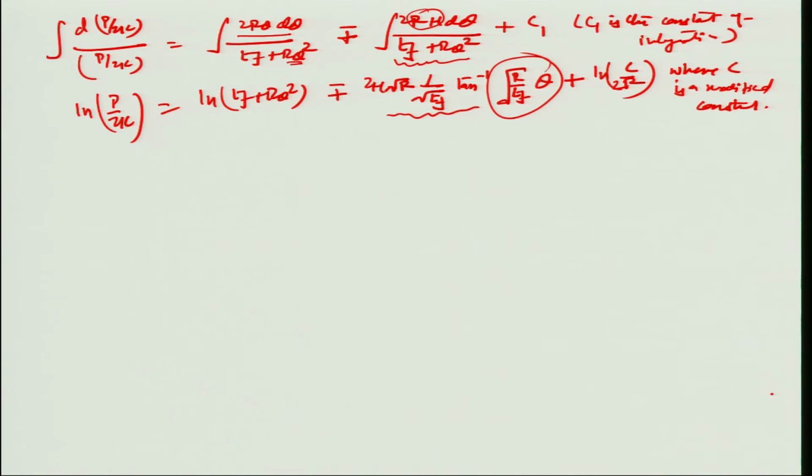So therefore, if this is going to be the final solution for the indefinite integral, the goal that we must have is to be able to estimate what is going to be the C value, for you to be able to tell exactly what is the roll pressure which is needed to set forth the yield criteria of rolling, which is as per von Mises, as we have developed earlier, as P plus sigma x equal to twice of k, where k is the sort of ultimate shear yield stress of the material.